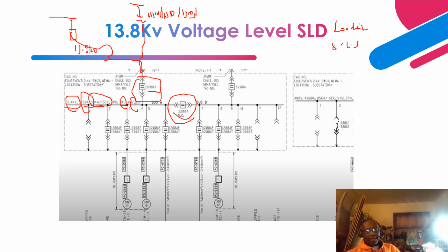On the other side, similarly, like I told you, you have a redundancy that has been put into this design. So this probably is fed from another 13.8 kV switchgear with a dedicated breaker from somewhere. Basically this is fed into. So this breaker that you see over here is part of this switchgear. There's an incomer cubicle main breaker. They call it main breaker or incomer breaker, depending on where you are. Sometimes in oil and gas they call it the incomer breaker. This is the rating of the breaker, 3200 amps.